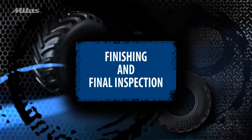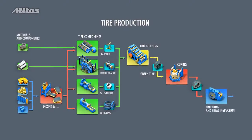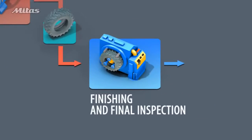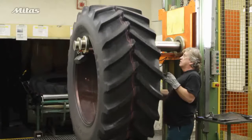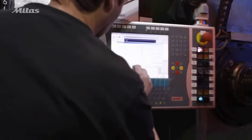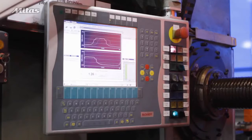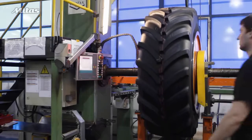Finishing and final inspection. Before the tire is dispatched from the plant, it is trimmed to order and inspected. Each tire is visually inspected for surface defects. Testing machines measure the compliance of central and lateral runout with the norms. All tires undergo a uniformity test. Tires containing steel cords are inspected by X-ray for internal defects.